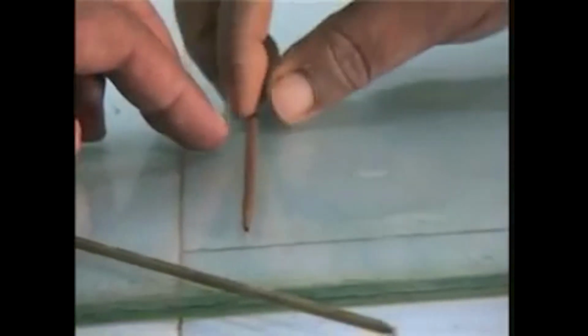And you can see that this could actually be rolled to 3 mm size, and the sample didn't crack. So we need to have a little bit drier sample, and if it is slightly drier than that one, then we won't be able to roll a thread of 3 mm size. You will see that in the next little bit.